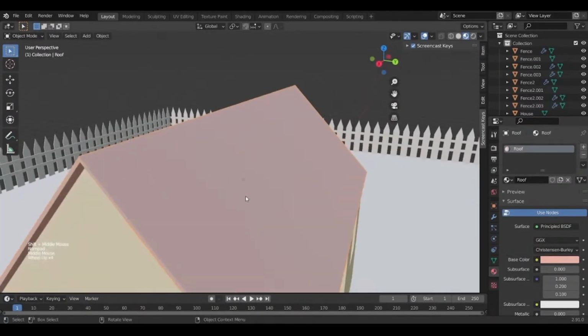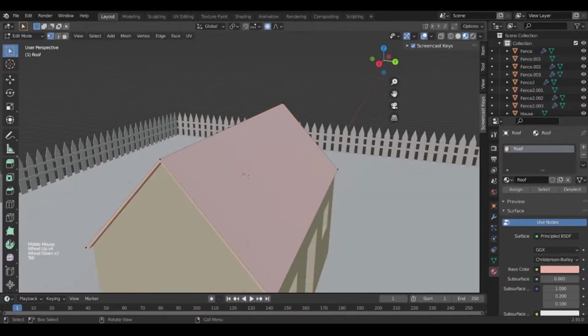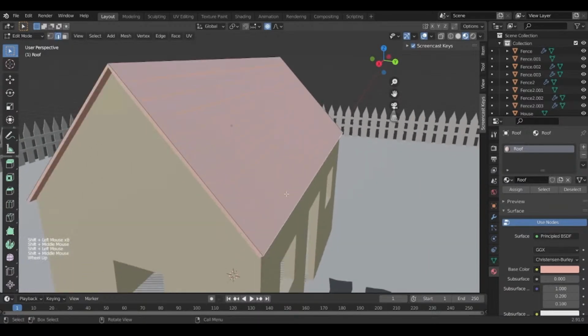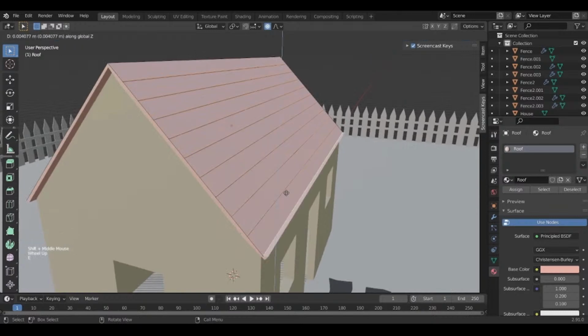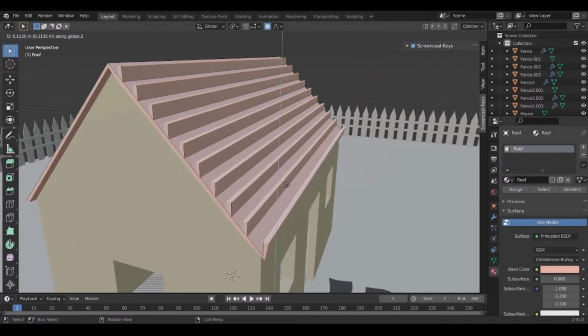So I'm changing the focus and then edit mode. And then I can add extra edges here. Then I can select all of them using 2, then Shift. Press E to extrude, Z to make it one way.